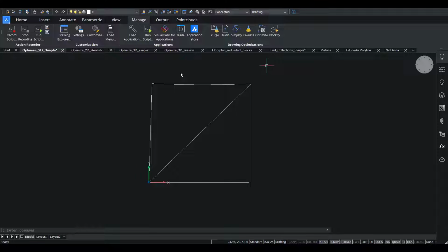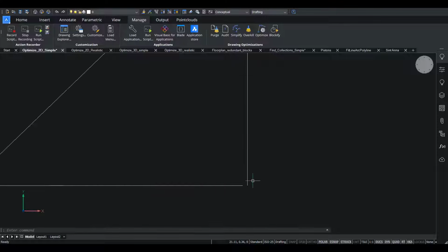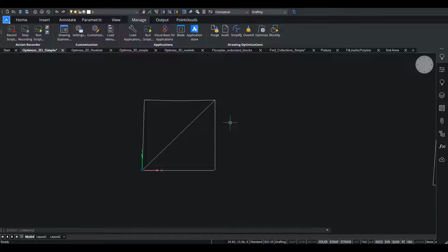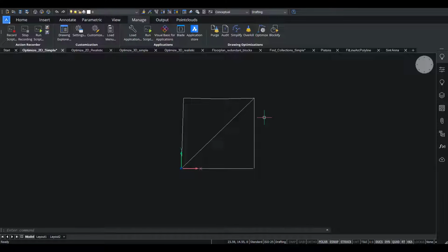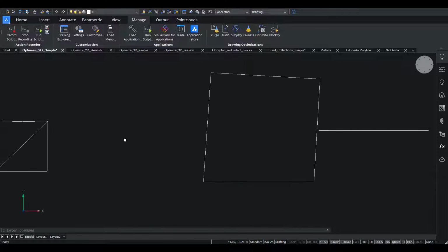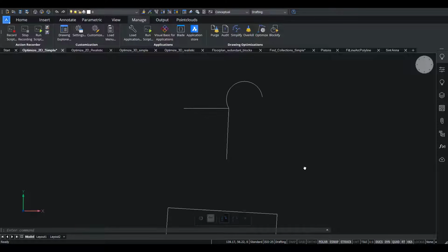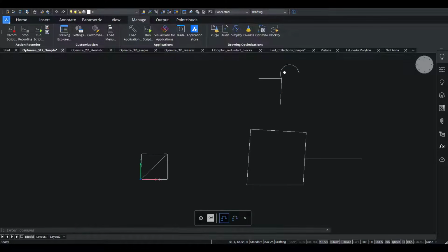One of these tools is Optimize, which was introduced last year, and the goal of this tool is to analyze the geometry in the drawing and to search for places where it can be optimized. This can mean, for example, to close the gaps between these lines or to rectify any skewed lines. This year we have extended the functionality to other supported optimizations. For instance, we have introduced the possibility to optimize polylines and arcs.